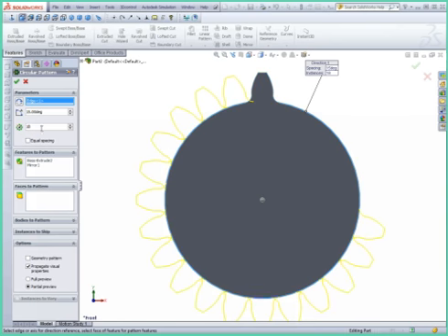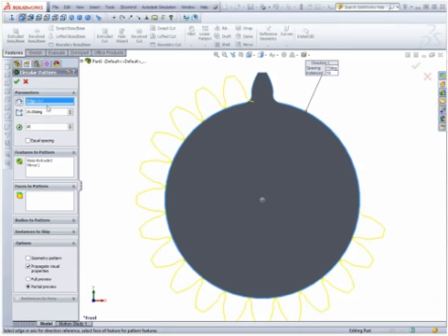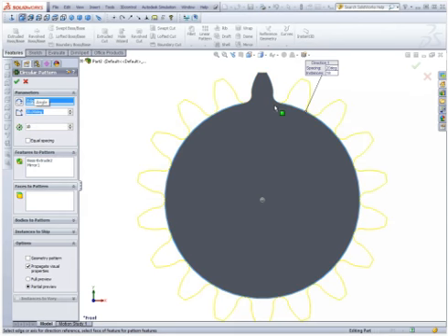And so again, this is an 18 tooth gear, so we already happen to have 18 there. Right now the spacing is not correct, and so if we take 360 degrees and we divide it by 18, we end up with 20-degree spacing between teeth. So if we change that to 20, now our teeth are actually spaced correctly apart.